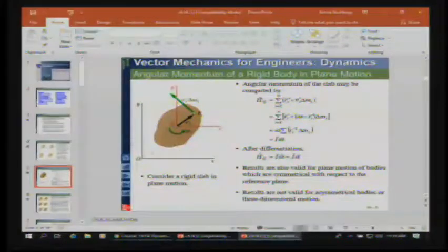That simplifies not only the motion, the velocity, and everything else, but it also means that mathematically all of our vectors of translation, our R and V vectors, are all going to be in that plane, and that makes our alpha and anything rotational in the pure Z direction. So it simplifies us from essentially 9 equations to 3 equations. So the simplification is pretty significant.